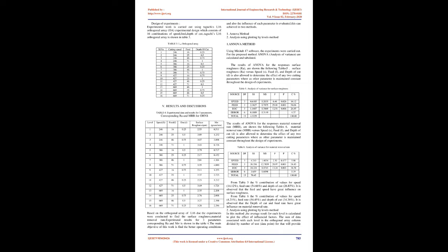Joshi et al. investigated the SR response on CNC milling by Taguchi technique. Analysis of variance, ANOVA, was used in this investigation. The material used for the experiment is 100 x 34 x 20 mm, 5 blocks of aluminium cast heat treatable alloy. The output characteristic, surface finish, is analyzed by software Minitab 15 and ANOVA is formed, which shows the percentage contribution of each influencing factor on surface roughness.